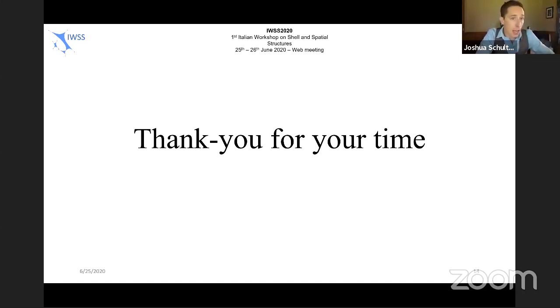And the good news for that is that when you think about laying up these panels, the transverse plies as a structural engineer give me no real strength or no bang for my buck, right? So there's no practical reason to thicken those plies. In fact, what you'll oftentimes see with these CLT panels is when we go to thin CLT panels, we thin out the transverse plies because the longitudinal plies are doing all the work. But it's a great question because that definitely breaks down one of our fundamental assumptions in the equation.